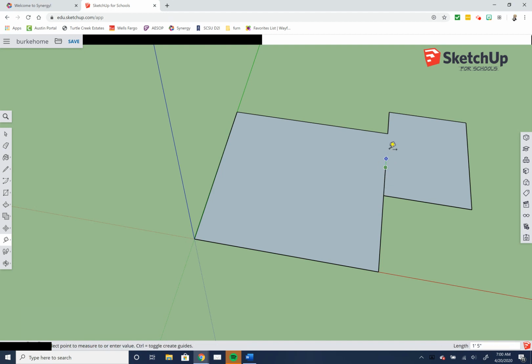Then I can go from this line to the opening of my door. The opening of that doorway is 5 feet, 8 5/16 of an inch. Okay, so that's a pretty wide doorway. Now, your doorway has to be at least 3 feet wide. I can have a wider doorway, that's not a problem, but you want to make sure your openings are the right dimension for your home. Okay, so now I've got a good bedroom here, so I would figure out the rest of the layout for my room.